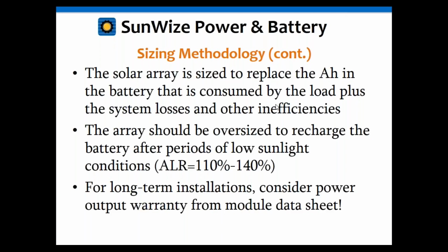A lot of people think a bigger battery is better. It isn't always better, because if you go with a massive battery, say maybe a 30-day battery, and you drain the battery down, and you've sized your array very small, maybe just 10% over, then it's going to take a very long time for that battery to get back to a full charge.